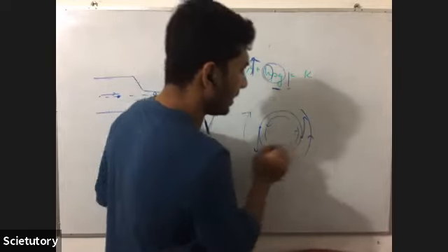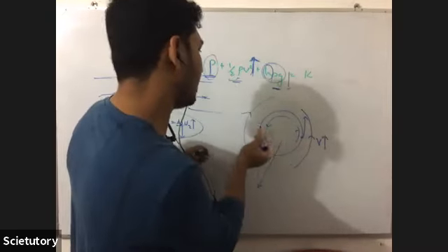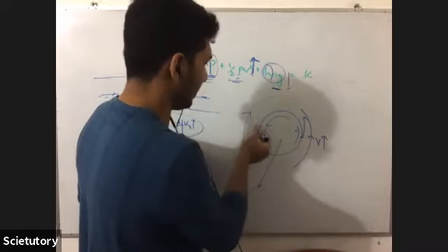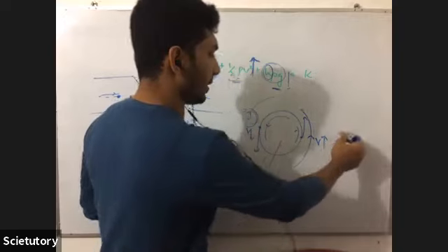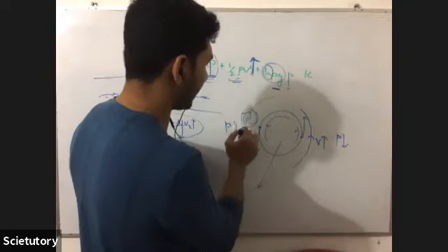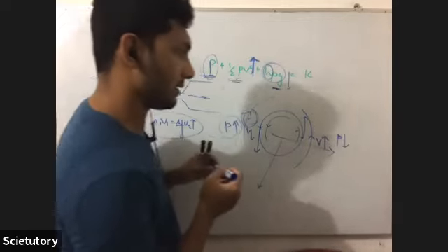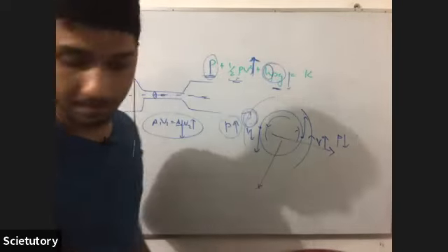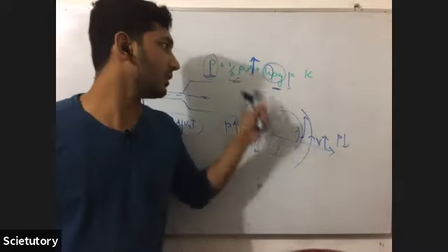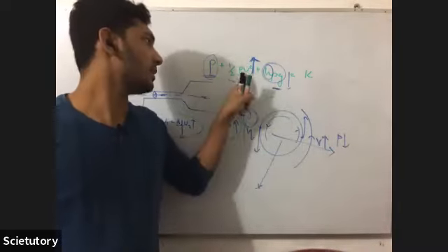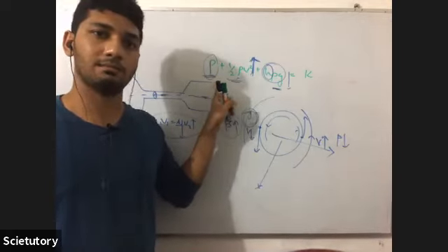Here the resultant velocity is high. Here the ball is opposed by the air, so the resultant velocity of the air is low. So the pressure here is low and here the pressure is high. With the higher pressure, it is deflected like this due to the resultant force. So scenario C is explainable using Bernoulli's equation: with increased velocity, decreased pressure.